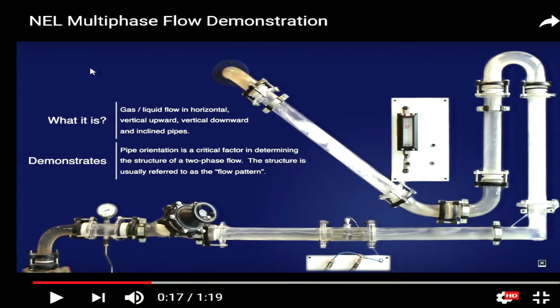Okay. And then you see also a classic example of churn flow. From time to time, the void fraction, the amount of gas in the cross section, increases and then decreases, then increases, then decreases, and this causes flow reversal. A part of the flow actually is turning back on itself. Okay. I am going to show you a high speed video in very slow motion, and you can see this classic example of the flow turning on itself.